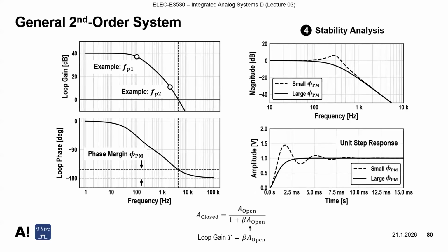So when we open our textbook, you may find this kind of graphs. For smaller phase margin, you may find that our magnitude has this kind of gain peaking. For larger phase margin, we have a very smooth low pass filter response. For the small phase margin, you will find your transient response looks like ringing, as we discussed, because of the sine term, right? And the fluctuating. For the large phase margin, it is okay, going to smooth conditions.